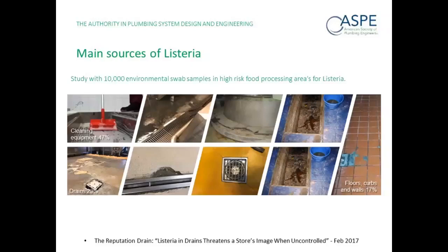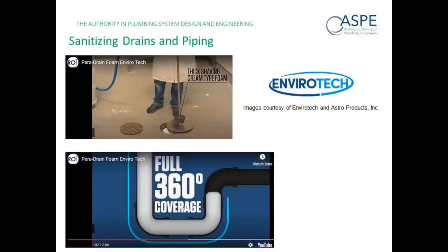So almost always it's going to be root source analysis in the drain, and then any connections from the drain, usually the drain to the floor, just because you have dissimilar materials meeting together, or the floor to wall interface. Anywhere a material is starting and stopping, if there's a gap, that's a place for life to occur. And once they start trying to clean it, the next thing you know, they're using high pressure water, and you've now aerosolized the Listeria to stick on different types of surfaces, such as walls and actual food itself.